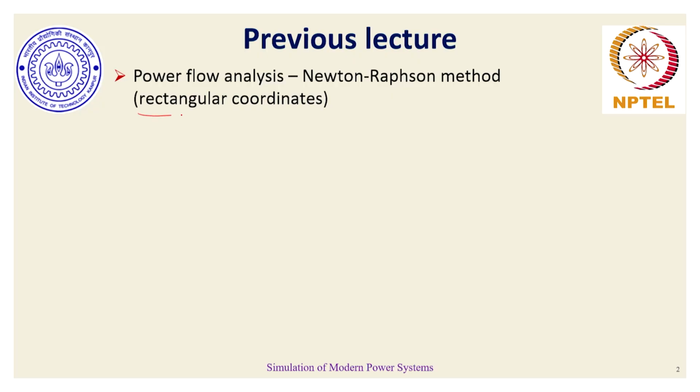In today's discussion, we will solve participation factored power flow using the Newton-Raphson method with bus voltage phasors in rectangular coordinates, so that the discussion that we have had for bus voltage phasors in rectangular coordinates gets further solidified, and the explanation of participation factored power flow also becomes clear. It's not that participation factored power flow can only be done for voltage phasors in rectangular coordinates. It can also be solved when voltage phasors are in polar coordinates. The discussion, however, would remain the same.